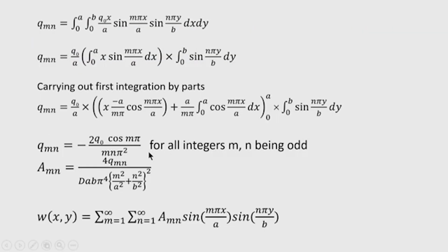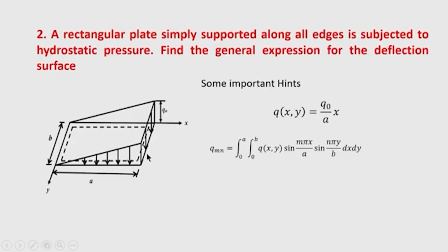So, what we have done in today's class is we have illustrated the problem of plate on elastic foundation. Then I have discussed a special problem where a triangular shaped plate is taken, and the plate is equilateral and subjected to moment along the edges. This moment, of course, the magnitude is taken equal and it is symmetrical, that it is trying to sag the plate. So, under the action of this edge moment, we have found the deflected surface of the triangular plate, and from that we have found the expression for bending moment and twisting moment.